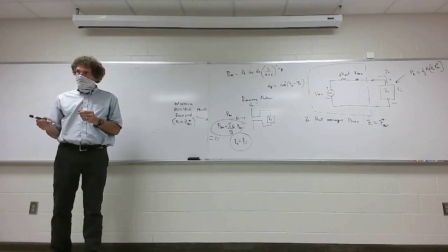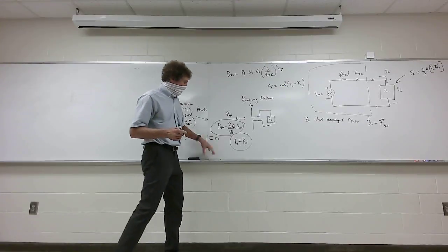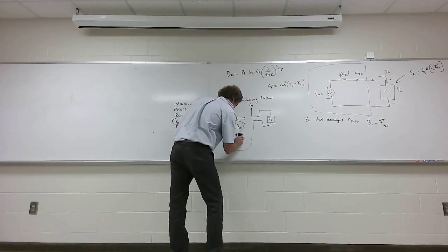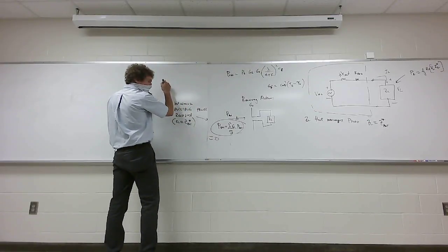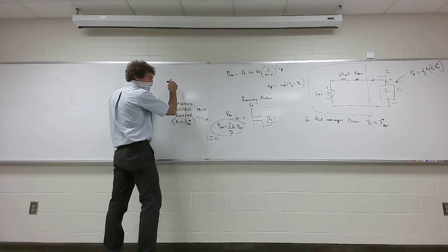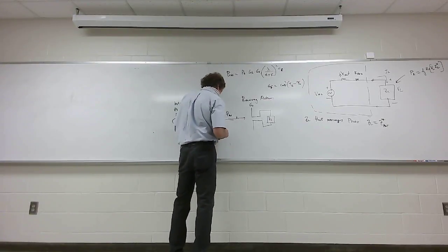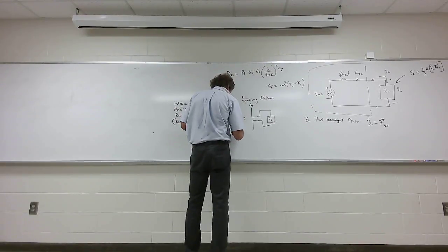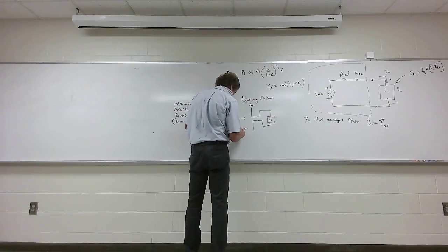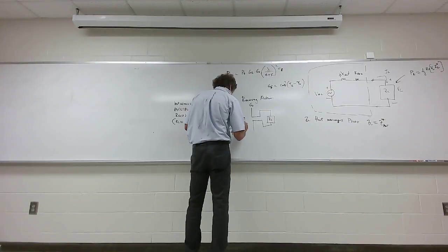Yes, sir? What does that equation say, on the bottom, I can't remember. This? It's RL equals RS for maximum power. No, I meant on the VP of VOC equation. Lambda squared over 4 pi times gain received. I can put that again. It's lambda, the wavelength squared, over 4 pi, times the gain of the transmitting, gain of the receiving antenna, right there, times the actual aperture.